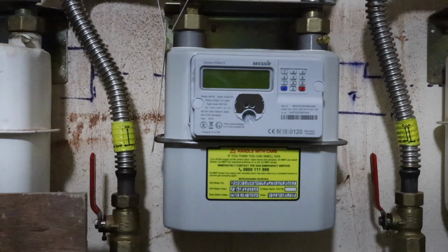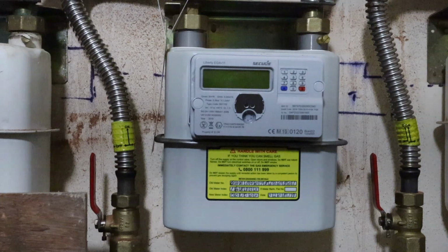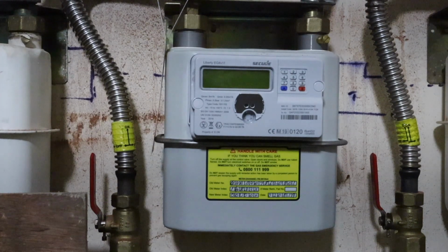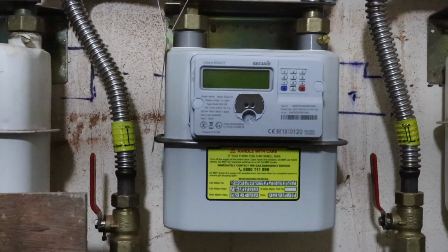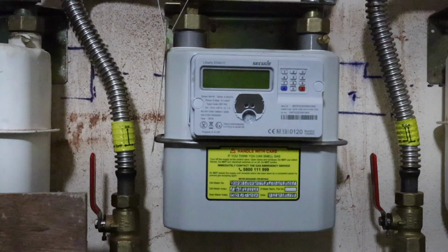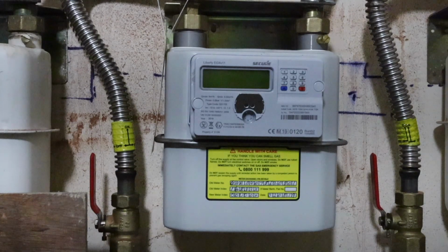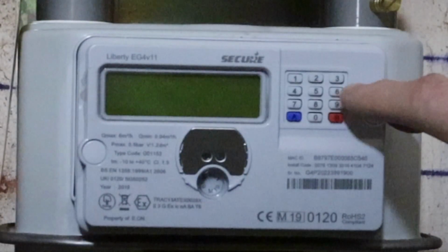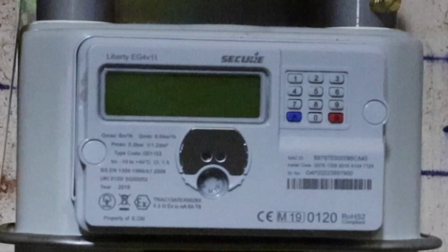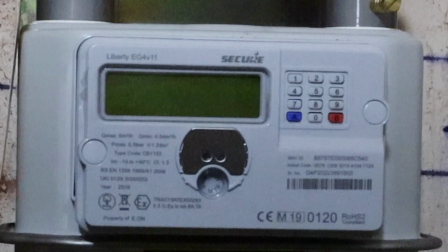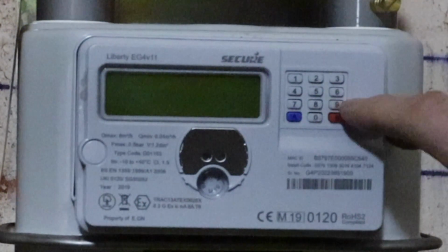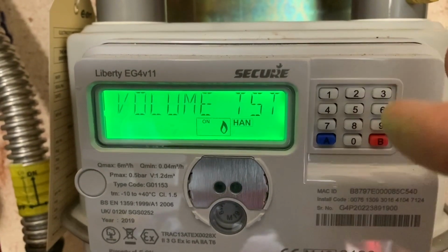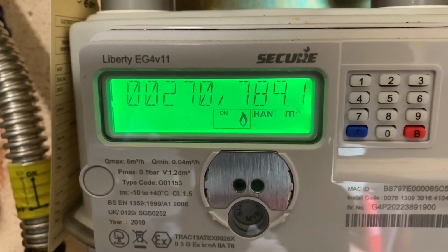So once we've got to the volume test, for 2 seconds this meter will display our reading, but it will give it us to 4 decimal points, but we only need 3 decimal points. So first thing we're going to do is we've got the appliance set on full. We're now going to press the number 9. When we press it the 3rd time, we start the stopwatch and then we time it for 2 minutes. So it's 1, 2, 3, comes up volume test.